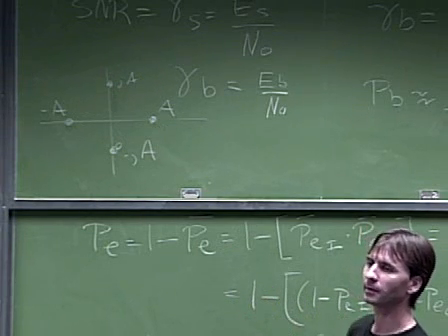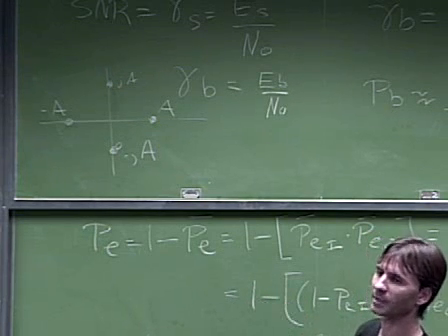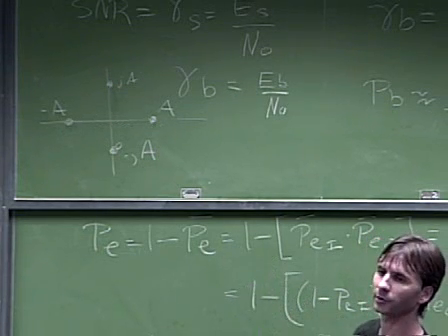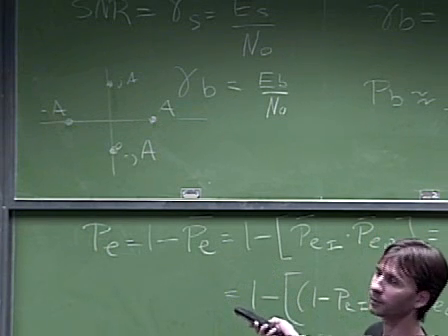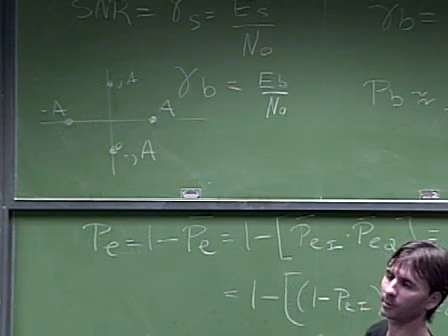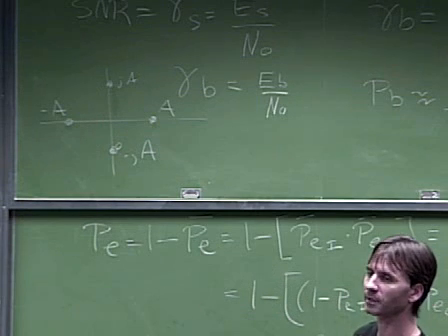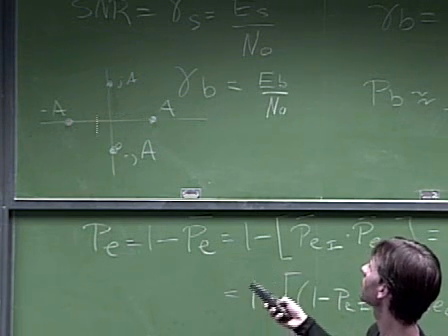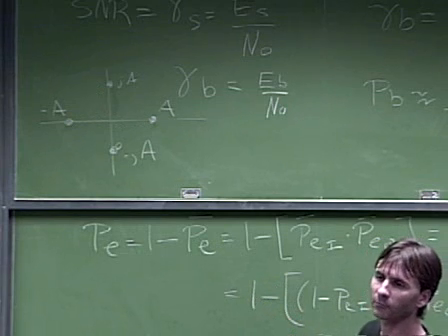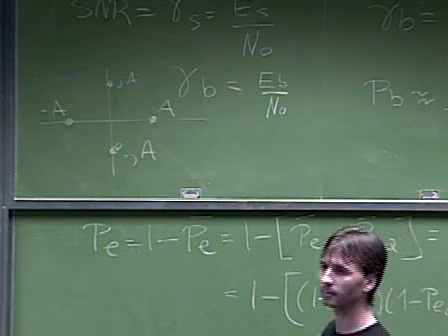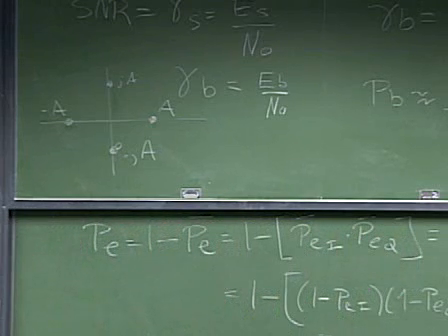Imagine I give you a noise that doesn't have this property. For example, imagine I give you a noise that is stronger in phase than in quadrature, right? Then this wouldn't be true anymore, right? So I need the noise to be symmetric in all possible ways. And Gaussian noise is, but it could be not so, right? For example, if you had impulse noise that only has an in-phase component, this would not be true, right? So it is not universal, but it is true for our case. Now you're correct in that most of the time, when you do make a mistake, you're going to end up going to the point that is in the other BPSK, right? But it doesn't invalidate the derivation. Other questions?